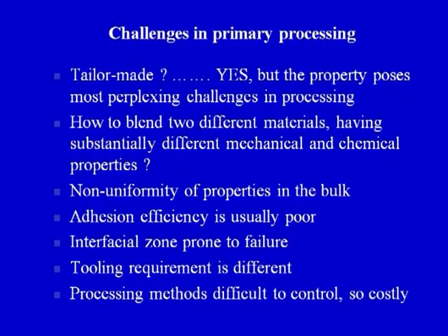So, we can say the adhesion efficiency is another issue. We have to see how the fibers should be used, whether the fibers should be given some treatment when they are being put into the matrix, so that the bonding between the fiber and the matrix is good, or the adhesion efficiency between the fiber and the matrix is extremely high. Usually, the adhesion efficiency is sometimes poor, therefore the resultant composite is not able to bear a lot of load, the type of load that the composite has been designed for.